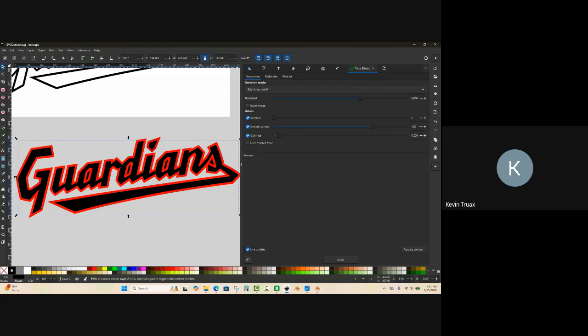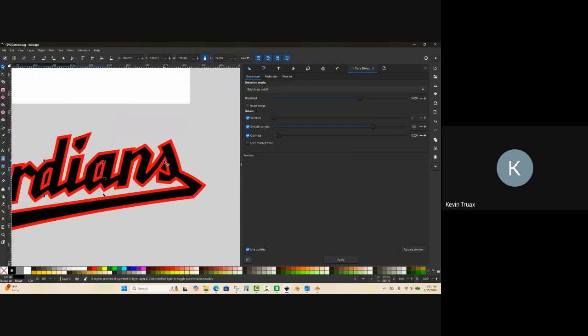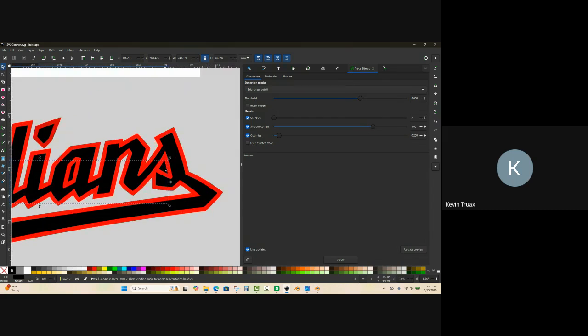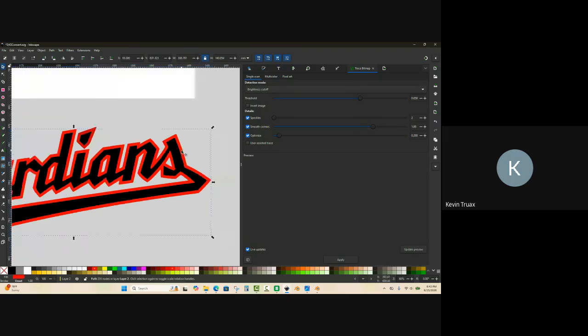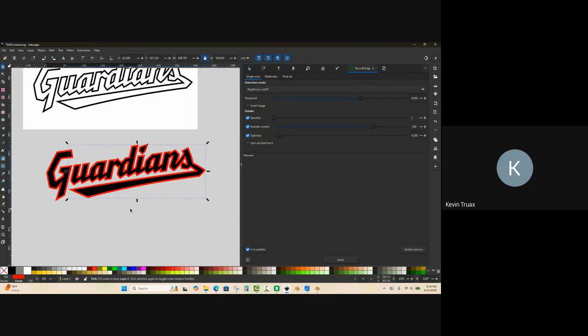So now we've got that going on. And then what we're going to do is all these interior pieces, we're going to select them. There's 1, 2, 3, 4. We're going to combine those into one because we can only have one cutter. So Control plus, that is union, or we could have done Control K, either one. But then we're going to take the black bits here, shift click the red, Control minus. So all those areas are now dropped out, okay?